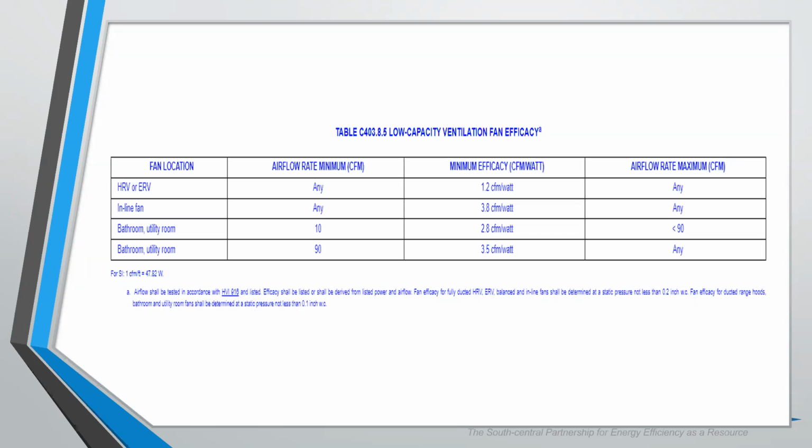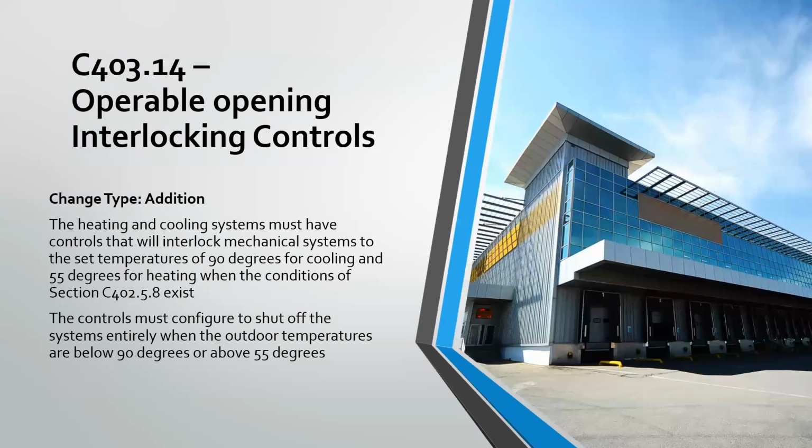You can look at the manufacturer specs. Usually there's a sticker or a label that's posted on the fan itself, and you can look at that. Or if you're looking at the design and a list of equipment, make sure that those are installed and that they've used the one they've deemed in the design. You can see that and look at the watt draw and CFM rating capacity for those fans, making sure those meet that requirement.